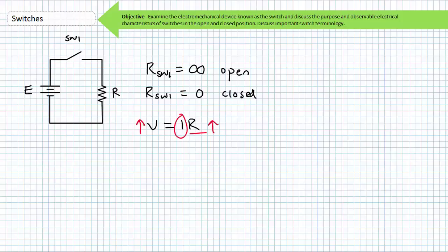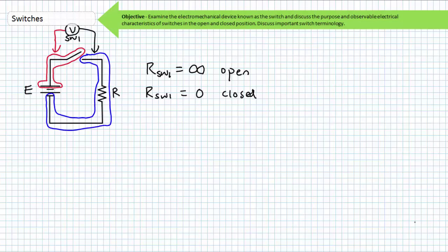Given a closed switch is idealized as a 0 ohm resistive path, it can be stated that no voltage will be dropped across the switch when it's closed. Additionally, given an open switch is idealized as an infinite resistance, and you can't get much larger than infinite, this presents the largest resistance in the series path, and all voltage will be dropped across an open switch.